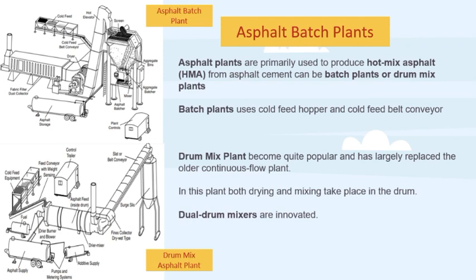The process is: from the dryer, hot aggregate is moved by a hot elevator into the aggregate batcher. Here it is filtered by the screen, by sizes, and calibrated feeders provide a supply of aggregate and mineral filler in the required quantities to the pug mill mixer.